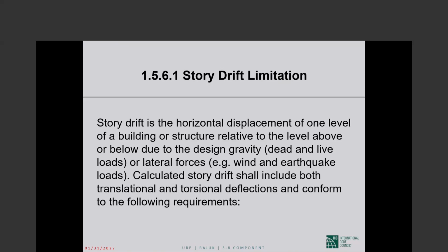The design wind force may act uniformly on the face of your building, or in design, we also consider the possibility that half the face is loaded with full design wind loads, and the other half of the face is not loaded at all with wind. That will give you quite a bit of torsion, and that may cause drift due to wind. So it is translational and torsional.